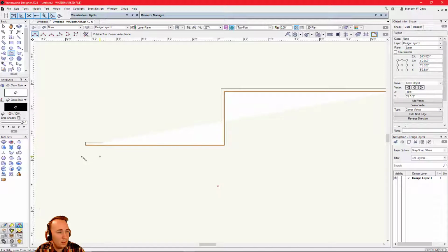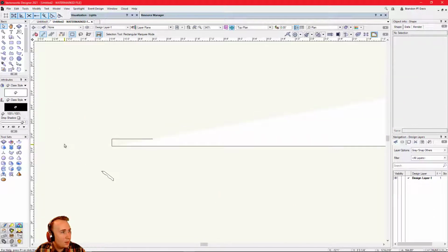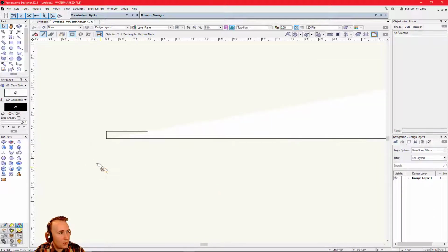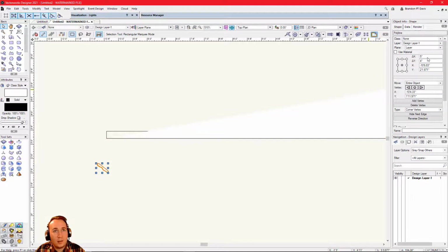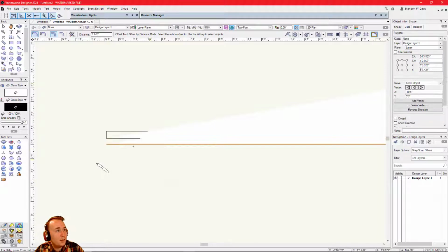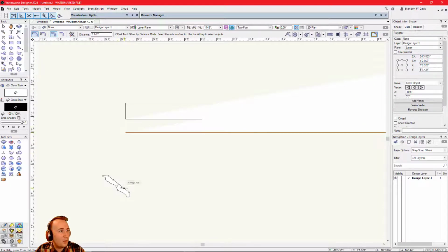But before we can do that, let me show you best practice: copy the x-axis. So I'm just going to right click and copy that. Then I'm going to use the offset tool. So with O, offset, I'm going to insert the measurement and divide it by 2. Offset that by half the width, because the Extrude Along Path tool is going to extrude from the center of the object. So I'm going to duplicate.